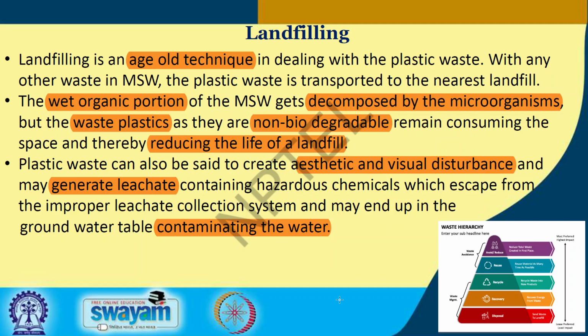So we need to think about landfilling. Landfilling is not simple dumping as it's happening in India. Landfill is a scientific engineered concept. We have to have a liner system, a covering system, gas extraction system, and leachate monitoring system, and every day we have to have a cell and cell cover, a daily cover. This type of scientific method is called landfilling. But what we are doing in India is called normal open dumping. We don't have any scientific landfill in India. That is another disadvantage.